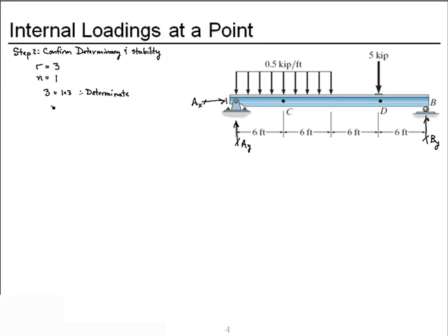We need to check the reactions to ensure that it's stable. The reactions are not parallel, they're not concurrent, therefore it is stable.